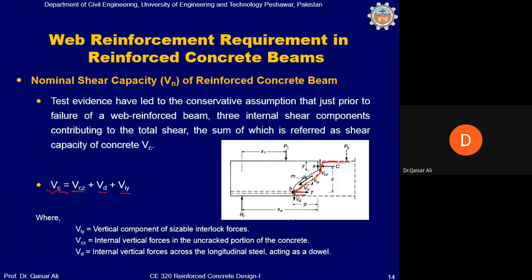if we join the other part of the beam on the right side, you will see that when these 2 sides are joined like this, there is a compression force at the top portion of the beam, and when you compress 2 blocks of concrete against one another, it will become difficult to slide these 2 blocks.